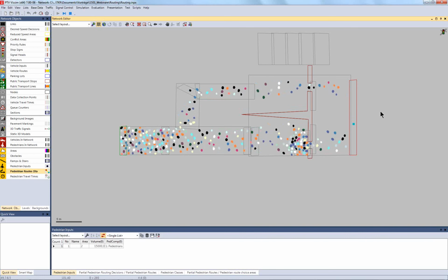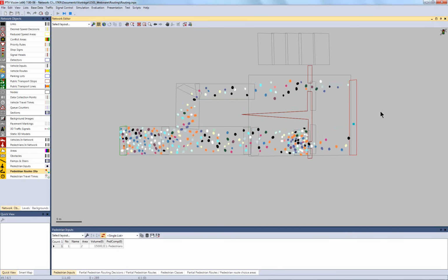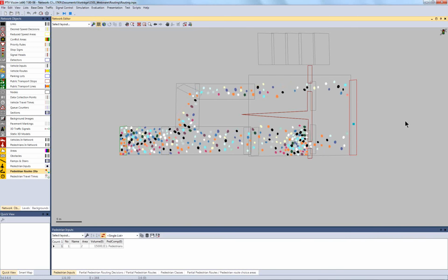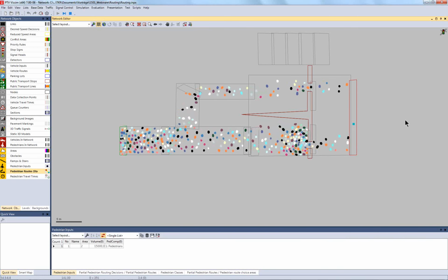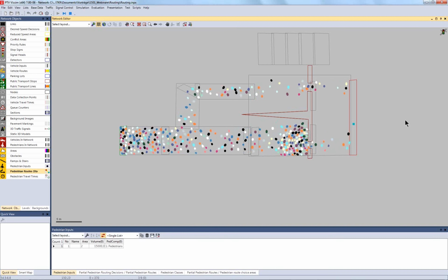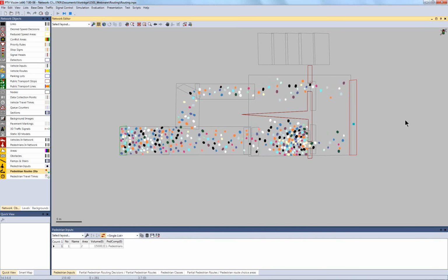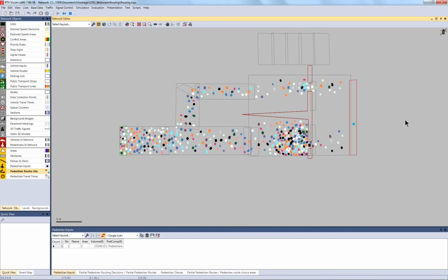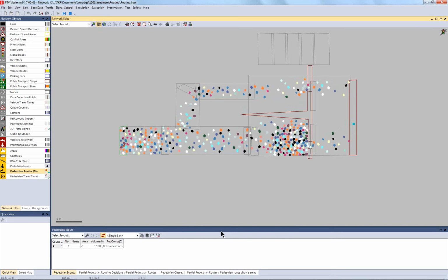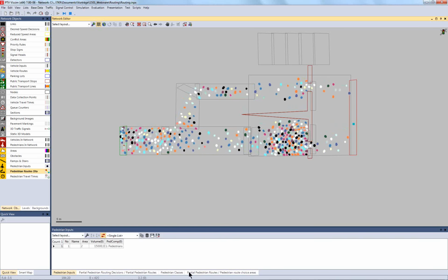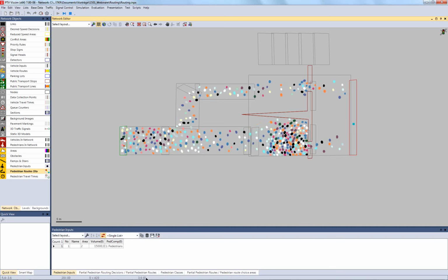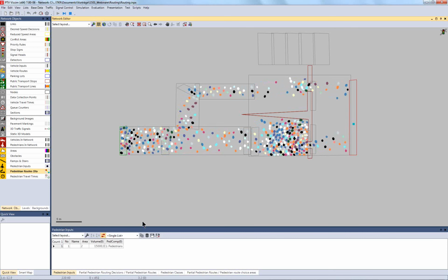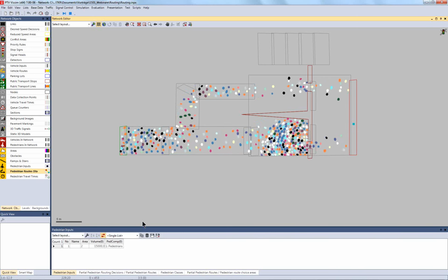So you have less work modeling, much easier, not so much to think about, not so much to worry about, just activating it and maybe the value of parameter G. But then in Viswalk, the simulation, the computer has to do more work, more computation steps have to be done, and the simulation runs slower. Here it's pretty okay still. We have still a factor of 3, 4 even compared to real time. But if you had, let's say, 100 dynamic potentials, then it can become quite slow.